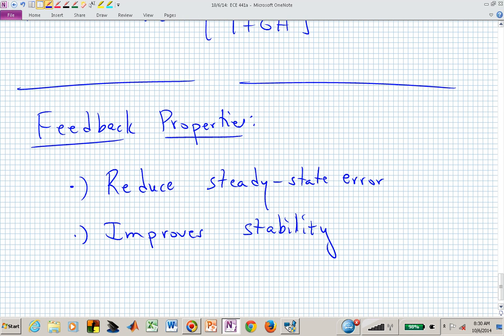What were some of your percent overshoots that you measured? 40-something%, 60%, pretty high percent. Where were your poles? So maybe you don't remember their numerical value, but were they not very far into the left half plane, but pretty high away from the real axis? Maybe like -1.5 up to 17 for the imaginary part.